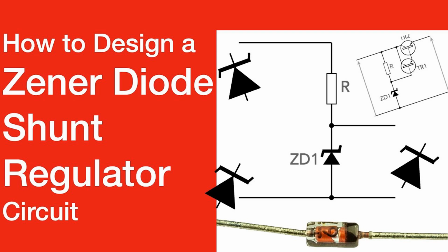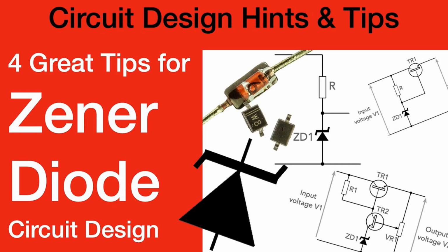Components: Zener diode, VZ. Series resistor, R. Input voltage source, VIN. Load resistor, RL, representing the load. Design steps. Choose the Zener diode. Select a Zener diode with a Zener voltage, VZ, equal to the desired output voltage. Example: for a 5V output, choose a Zener diode with VZ equal to 5V.